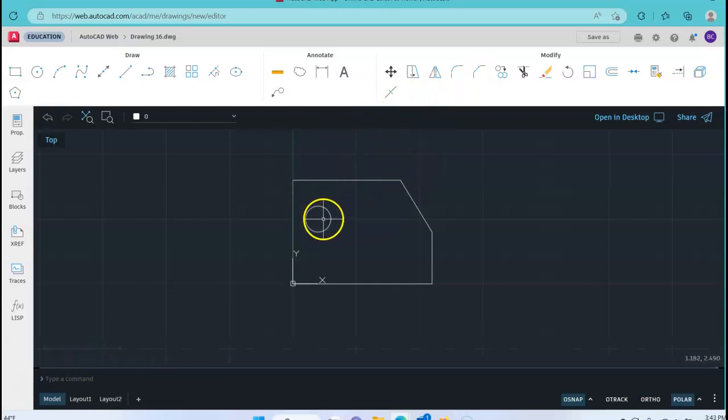It is very important to understand and look at that drawing to see the dimensions. That was 1 inch. That dimension is shown up here. So 1 inch over in the X, and it was 2.5 in the Y. That was the center. So now you take a look at that, and let's see if you can figure out what the center of the circle over here is based on the drawing given to us in exercise 2.